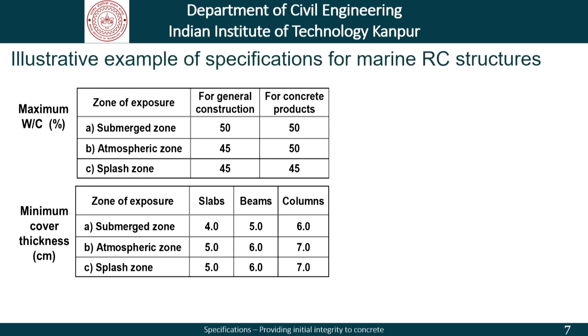Now, this set of data has already been presented to you, and I think we have talked about it earlier. This is basically an illustrative example of specifications for marine reinforced concrete structures. What is being done here is that the different zones of exposure have been defined and the maximum permissible water cement ratio has been defined for general construction and for concrete products.